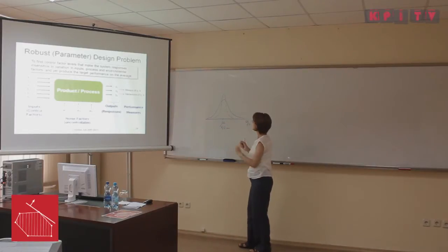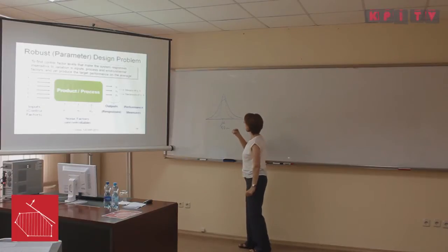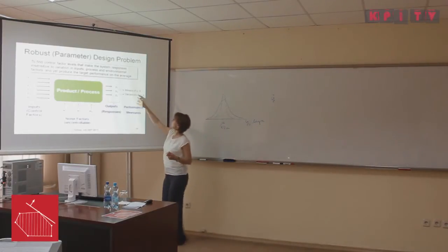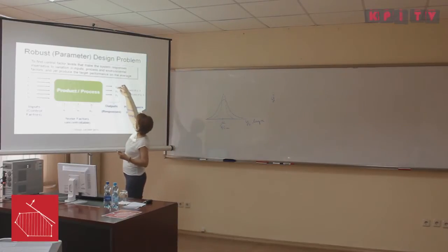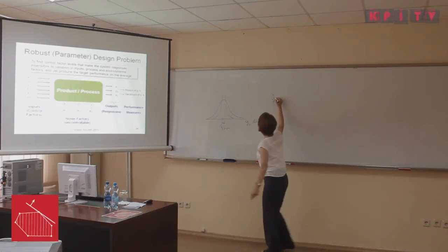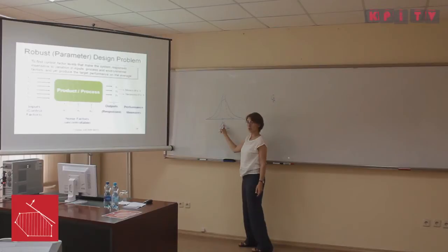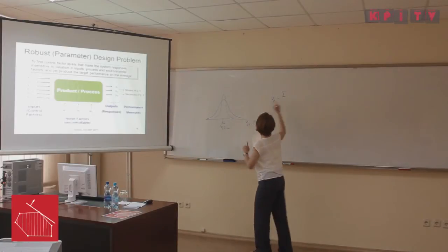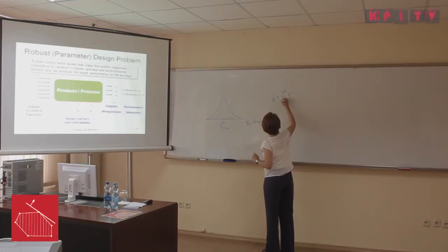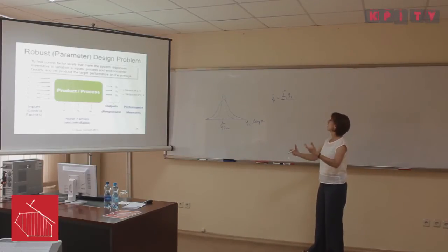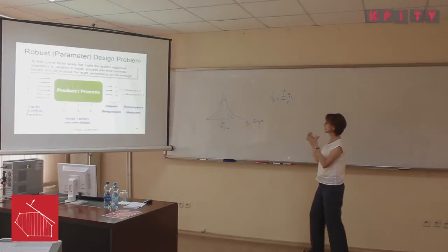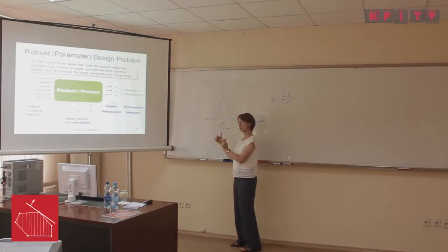This is a robust process, and if we see we are robust enough, we may want to look at the average of the parts that we produce. This is what we mean by the mean of Yi's. Take Yi as the length, and the average of parts is just estimating the population mean, which is the true average of all the parts that we ever produce. And that is a performance measure to us. We're going to look at that measure, the sum of Yi from i equals 1 to n, if we just take randomly n pendulums from our production line, divided by n. That is going to give us some idea about where the center of our production process is.